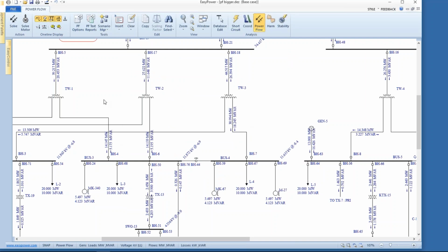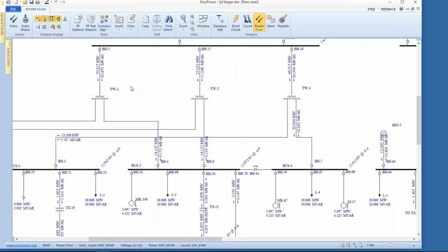And what jumps out at you, at least in some of these basic loads, is that I'm drawing almost as much in the reactive power as I am in the real power. So that's an indicator that there may be room for optimization in my particular design. We're going to look at the transformer taps.